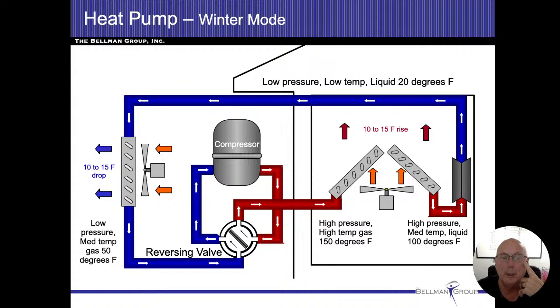And we don't want to put heat pumps on, what do you call those, setback thermostats where we change the temperature a lot, like a Nest where we'll lower the temperature or let it heat up in the house when we're at work, and then all of a sudden about a half hour before we come home, we turn it on and expect everything to drop. It doesn't work well that way. Heat pumps, when they're working for heat, we want it to stay consistent. All right, we want them to be on and maintain a steady temperature. That's when they work best.